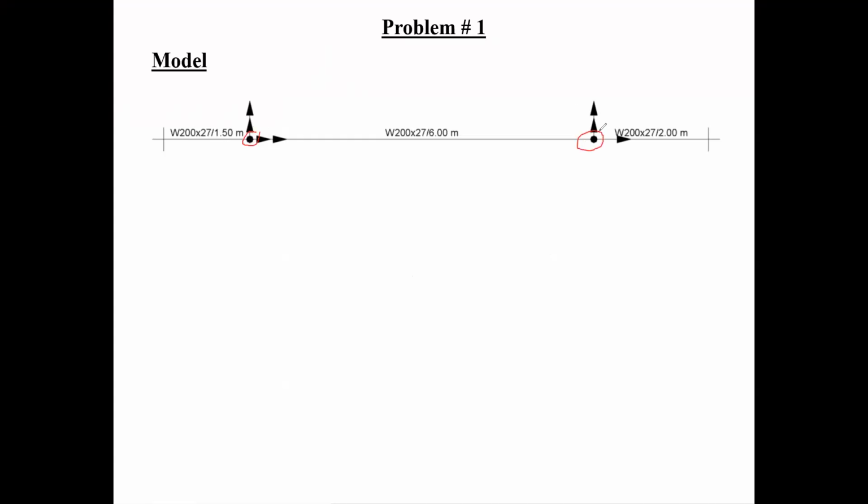And I'm going to repeat this one more time because it's very important, guys. You should try this on your own. Do an analysis with one type of support, do an analysis with a different type of support. You'll have totally different results when it comes to your analysis. I just want you to keep that in mind.